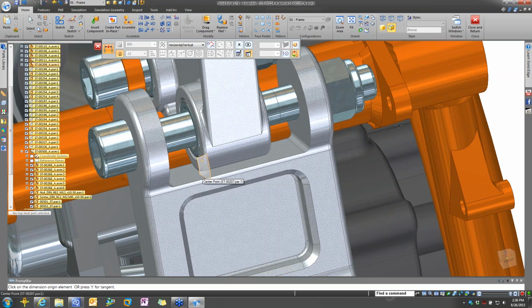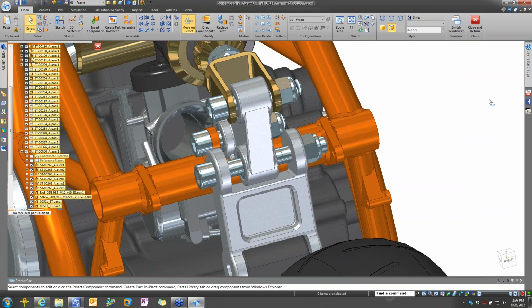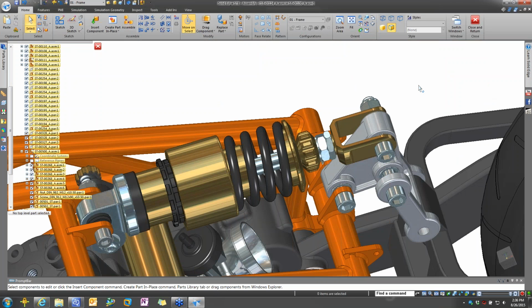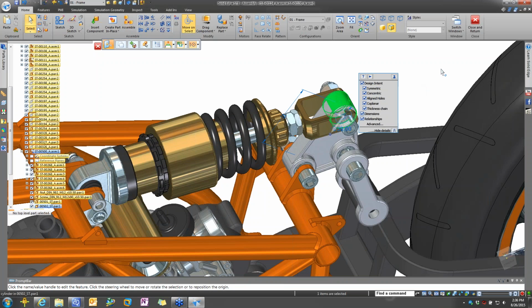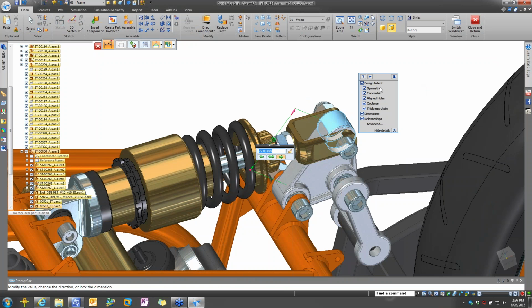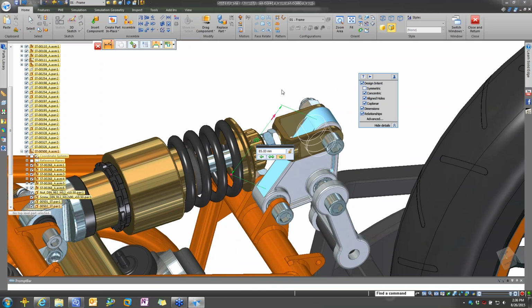if we want to get exactly where we want to place those dimensions. Or instead of doing that, and I'll show you another nice little feature, if we have placed any dimensions on any of the components already, I simply can just select any of those faces or features on that part, and again, any dimension that was placed on that component will automatically appear on the screen for us. So in this example, you'll notice that I may want to go through and maybe lengthen this part even further from 75 maybe to 85, and again, I'm doing this right here at the assembly level and making that change.